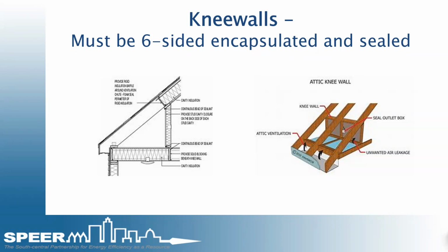The insulation is devoid of gaps. It has very minimal compressions at all, just to be able to uphold the R-value of that wall and not have heat transfer through that wall. Anything less greatly increases that heat load and is able to enter into the space by re-radiating into the space. Most of the time these are high enough on the wall that homeowners won't see it as a complaint issue because they're not standing next to it. But over time, it can heat up that space, causing an adjustment of the HVAC for more conditioning, and that just leads to more energy usage of the building itself.